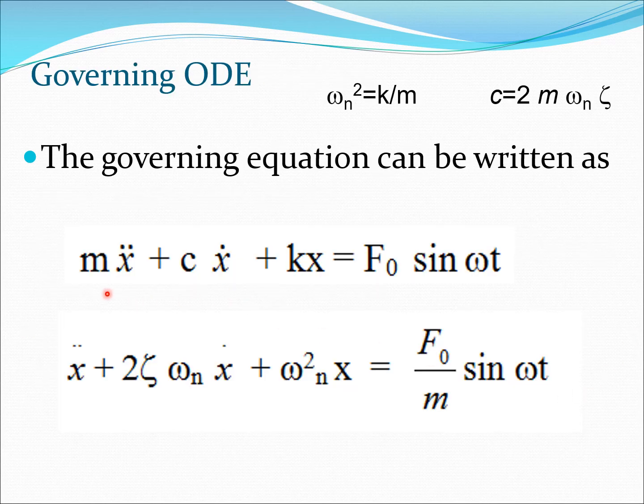So now we started with this equation, but many a time we can also start with this equation here, and you will see this in many books. In fact, this is a pretty favorite question in interview situations, that you may be asked to derive this equation and then you may be asked to get this form. And here the key step is that you divide this equation throughout by m, and then remember that k by m is natural frequency squared.